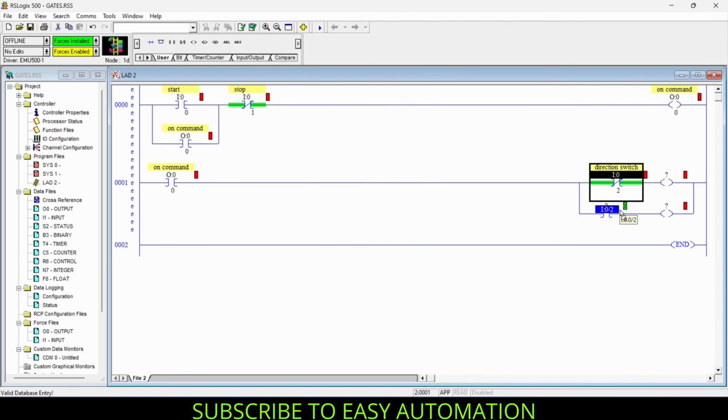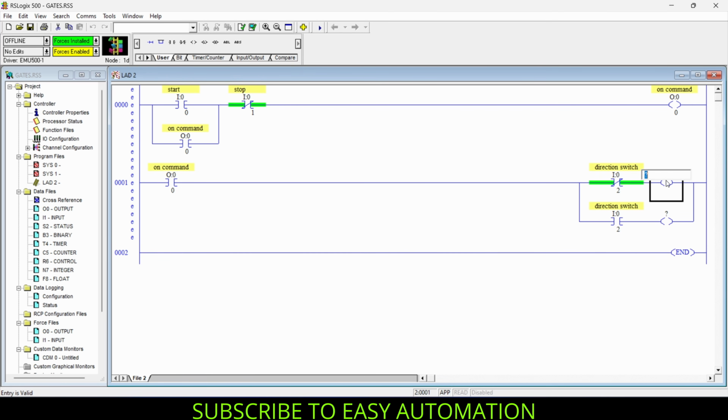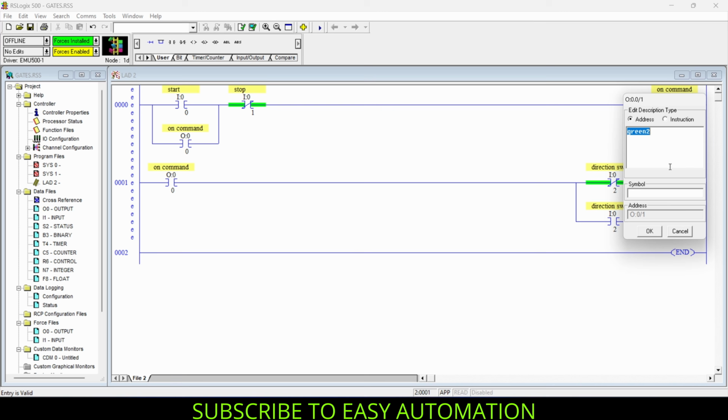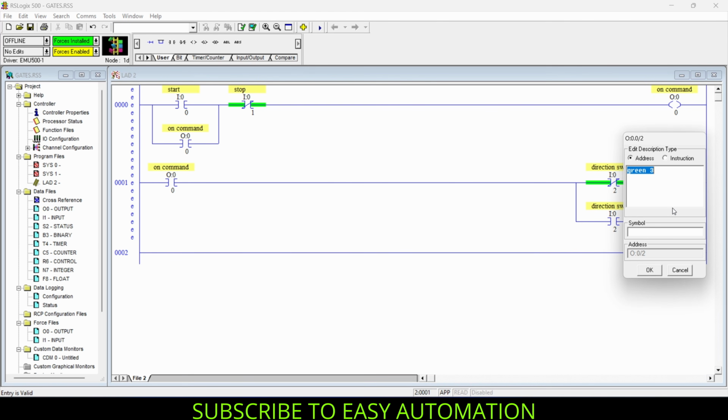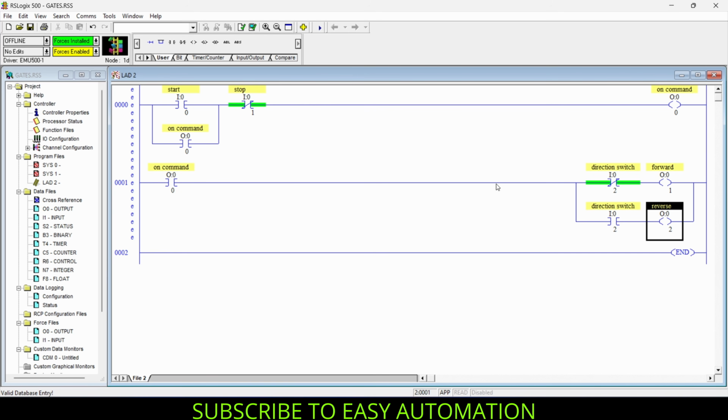So I will just copy this to our NO contact as well and give address to our output coils and name them as forward and give address to our second output. I will name it as reverse. Okay. So now this is the solution for our problem statement. So let's verify whether our program is right or wrong. So yes, verified and no errors found.